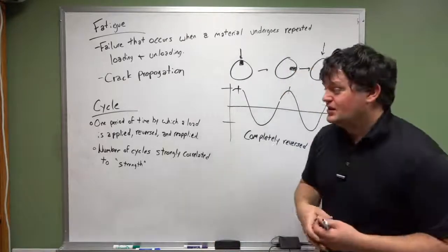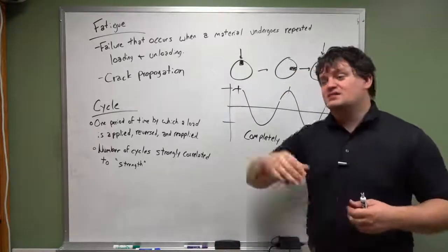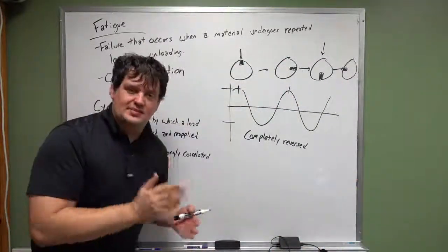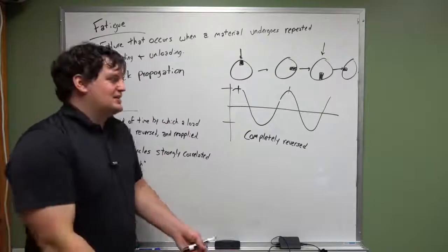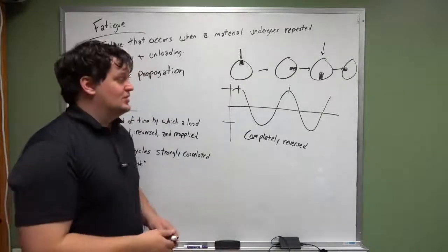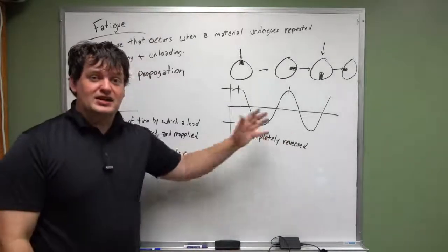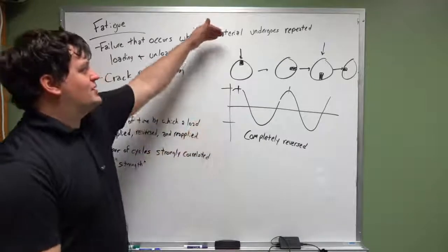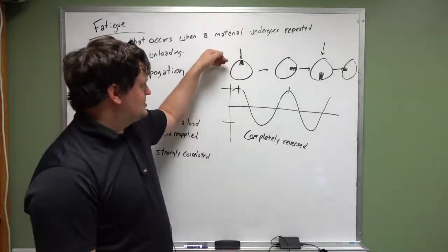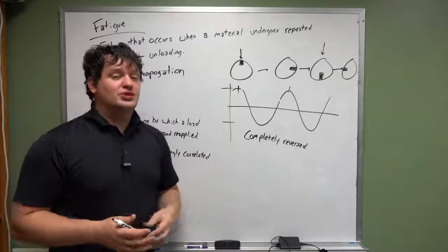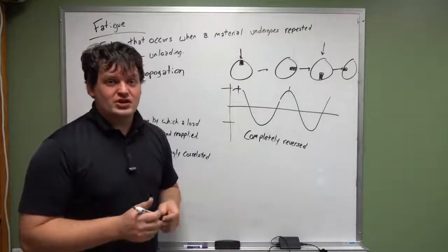My apologies. 1,000 times that, because it has to rotate that many times, and that's not counting the number of times it has to back up. That's not counting the fact that you may go beyond 200,000 miles. So having an axle that can handle 200 million loading cycles of being put in compression, tension, compression, tension, that's really critical for the lifespan of your vehicle.